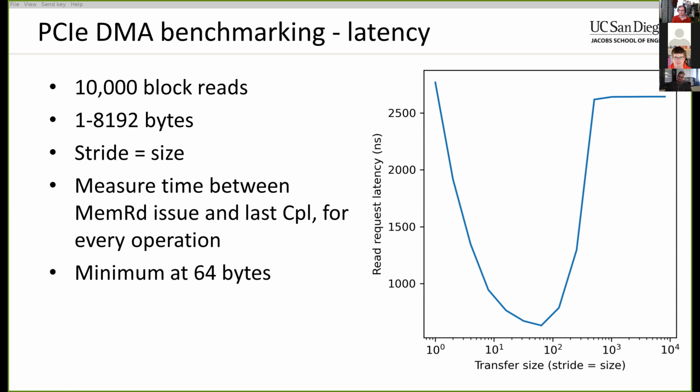With the variable length descriptor support, we'll read one big block, it could be 256 or 512 bytes or something, with multiple descriptors, and then those can just be returned from a block RAM cache on the FPGA. So that should produce a performance improvement, hopefully, once I get that working. After the core data path and logic is all done, then I can work on the variable length descriptors, and this is more motivation for why that's a good idea.